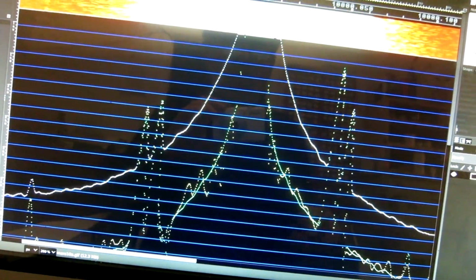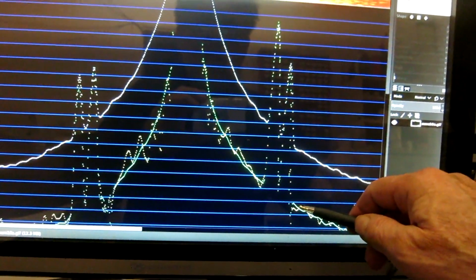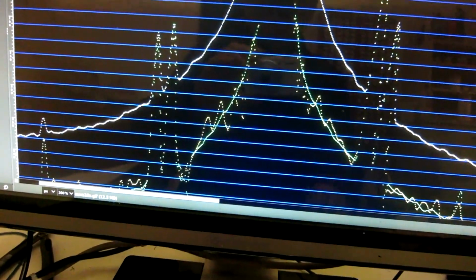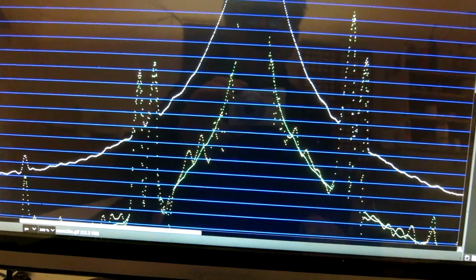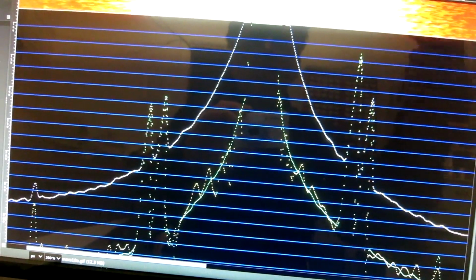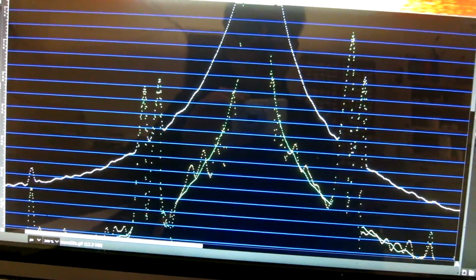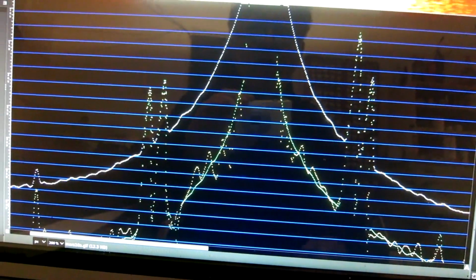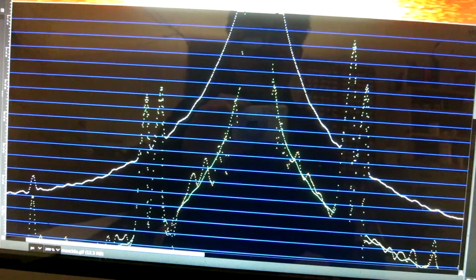And you can see also, of course, right above the 60 Hz spur we are here, but here we are on the bottom of the screen. So this will come clear from the table I'm going to make. The meaning of having different levels is that 50 Hz is AM as well as phase modulation. So the noise which is higher here, on the green curve, has to be phase noise plus AM noise, which is correlated to some extent.